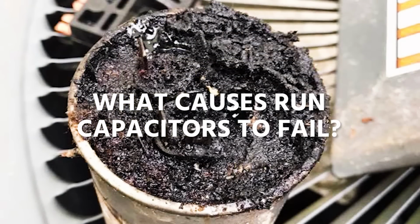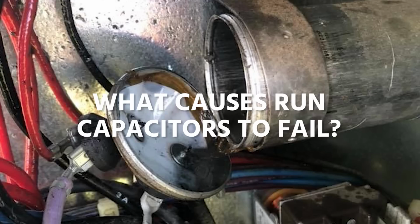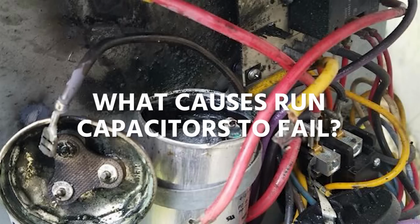A capacitor can store the electrons that are forced into it, but at some point it can't store any more, and that's dictated by the amount of pressure, which is why the amperage of a capacitor is dictated by the voltage applied to it, the capacitance of the capacitor, and the frequency. First off, if you're in the U.S., the frequency is pretty much 60 hertz. Now, could there be some cases, like capacitors installed in variable frequency drives, where you have various frequencies, and could that affect the capacitor? Absolutely, it could. But for most of what we do, it's pegged at 60 hertz, and in Europe and other places, it's at 50 hertz.